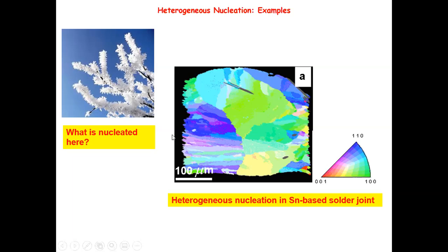And then due to the temperature gradient, because you touch the surface here, this part gets cooled very fast. So you have a large driving force for the small nucleus to grow. But because there are so many small nuclei forming here, when they start to grow, they impinge on one another, they're squeezing one another. So the only way they can grow is in this direction, and grow very quickly. So as you see why they have this very elongated grain structure.